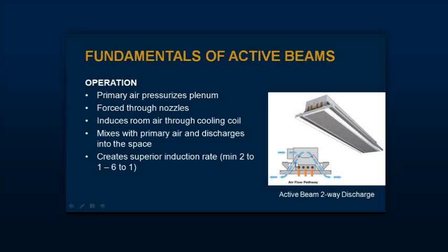They give you an aesthetic look that's different than just a flat surface, but also radiant panels, if they're completely metal surface, they reflect sound very effectively. And unfortunately, that would raise the amount of background sound inside the space. It might even sound like it's echoing. So we oftentimes have a perforated face with the sound-absorbing media on the back of it, so that it tends to absorb sound rather than to reflect it.